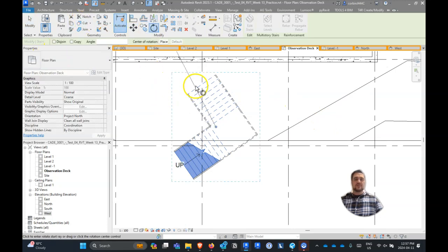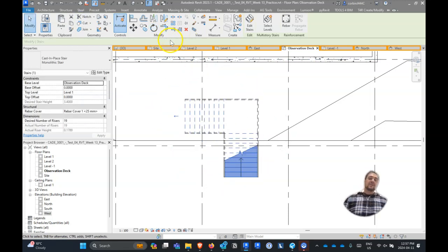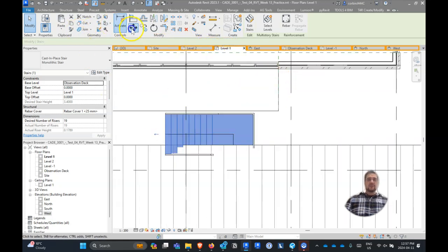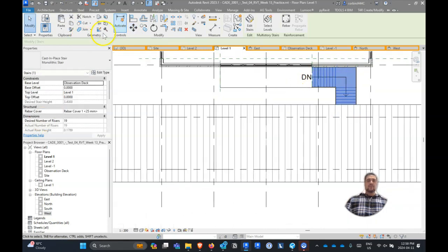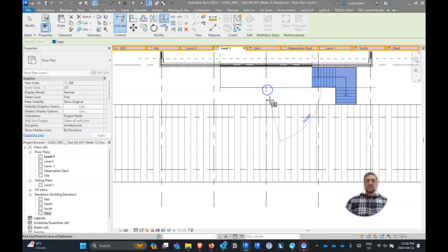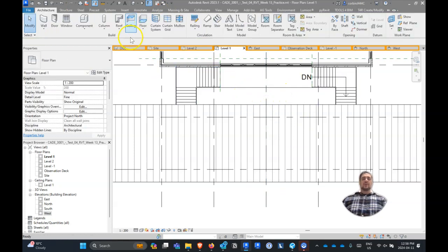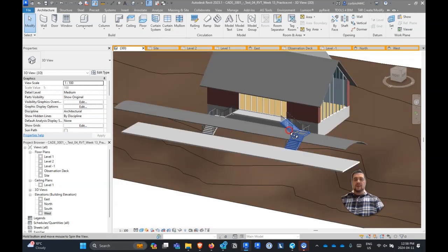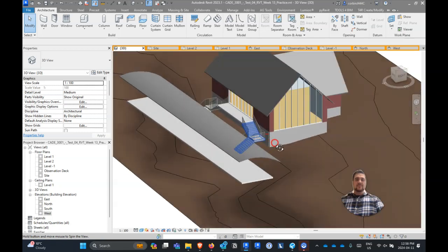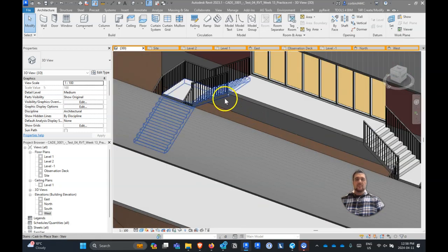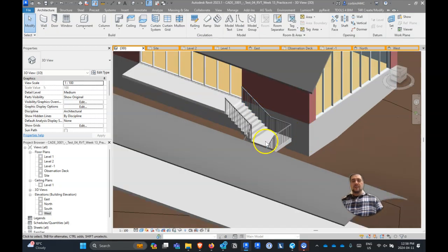So I'm just going to rotate this here. I'm going to use place. I'm going to grab the center. I'm just going to rotate this 90 degrees. And maybe actually this works out way better, because what we could do is have this stair on either side of our kind of deck here, and it goes down. And so maybe that's kind of a cool way of doing it as well. So we have this stair kind of on either side, and I just mirrored that over to the other side. And it kind of looks like we still have some head clearance issues. So maybe we need to adjust that a little bit more. So I'm going to delete the one side and go back to this side.